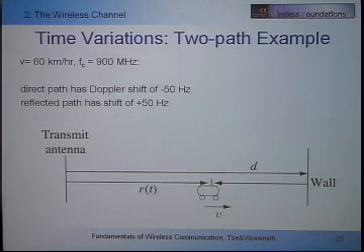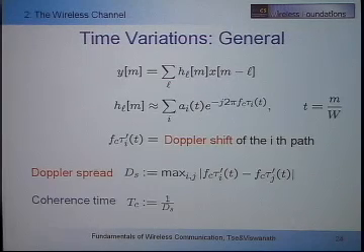Okay, so we were talking about channel variation with time. We figured out that the Doppler spread is an important number. The Doppler spread in turn depends on the carrier frequency, the speed of the vehicle, and also the angular spread. Now, I want to return to this channel variation question and look at our expression again. The nth channel tap depends on the gain of the paths as well as the phases. So when I talk about Doppler spread, I was referring to the variation of the phases.